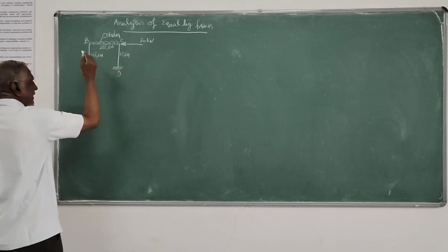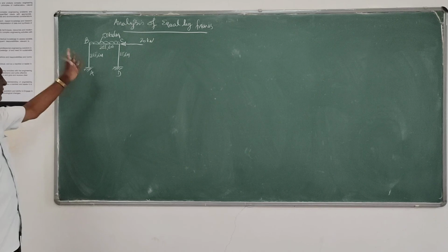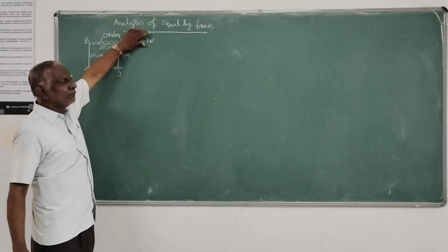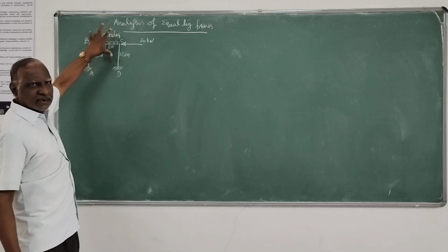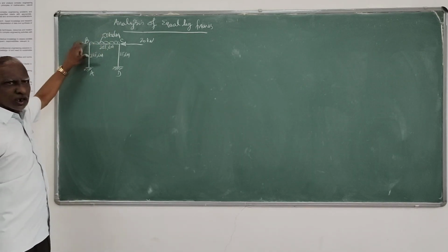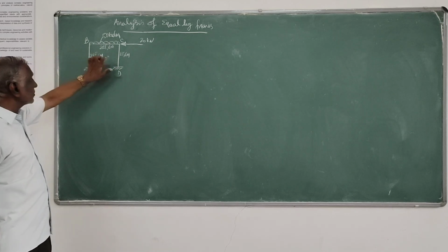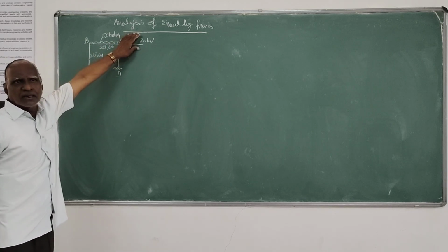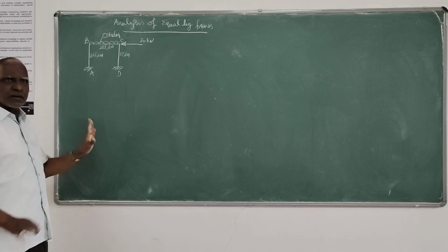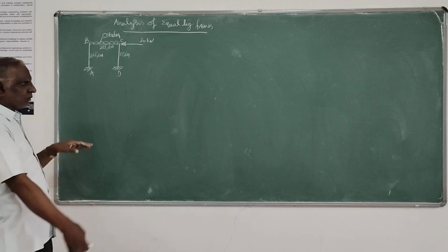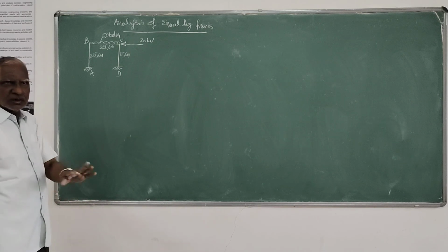So let us take this frame. This frame is definitely not symmetric, even if I don't have this load. It cannot be considered as symmetric because here one column I have taken 2EA, another EA. Otherwise this also would have been EA and this load was not there, then it was perfectly symmetric. You could have adopted the other procedure whatever I have just now completed.